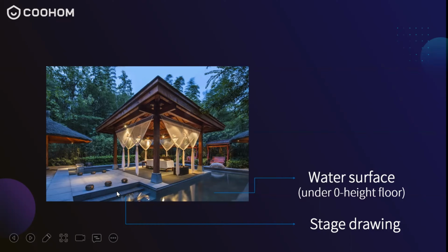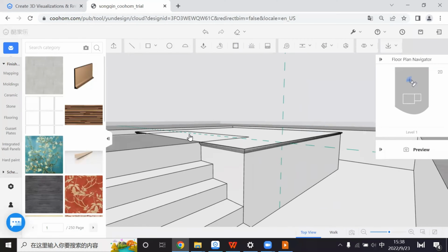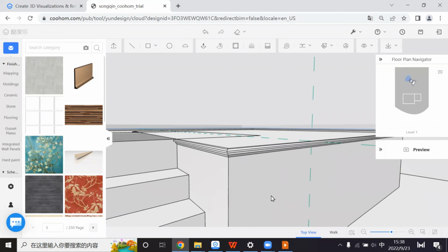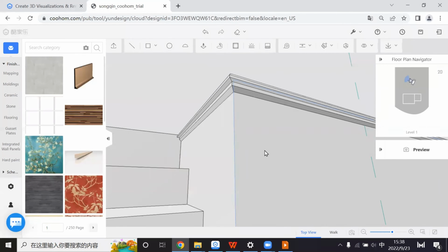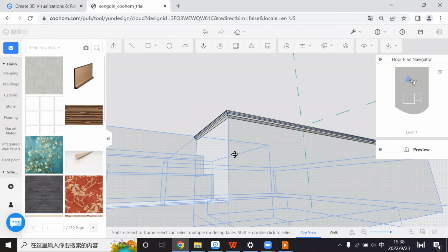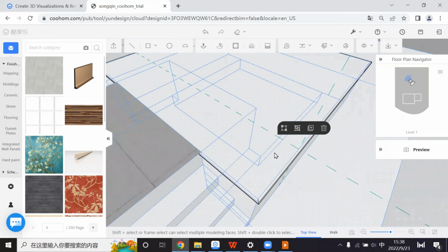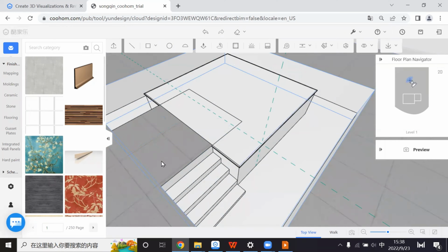But before that, I need to put some more material onto it. Okay, of course you can continue to use the concrete. You can use some more decoration elements. Here, a very useful way. Let's hold down the shift button, double click, and now all this construction free drawing can be selected, and you can click group. Once you group them up, you can just put the concrete material,